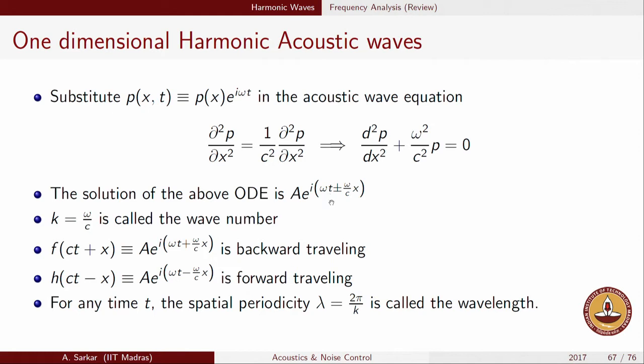Associated with the space dependence of the phasor, you will have a similar quantity which is called lambda or the wavelength, which by exactly the same analogy will be defined as 2 pi by k. So, the time period is the time after which the quantity is repeating, and wavelength is the space after which the quantity of interest is repeating.